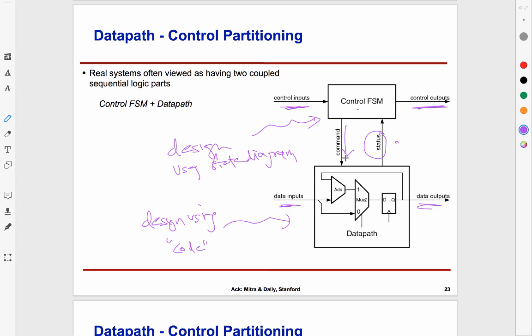So you can have that kind of logic happening out there. If you think in terms of your programs, then the if-then-else, for loops, those kinds of things usually get mapped to something happening in the state machine. Whereas operations like add two variables, multiply them, put them into a different variable, all those things are happening in the data path. So that's how the two end up interacting.